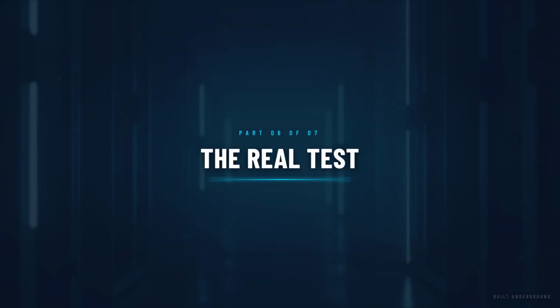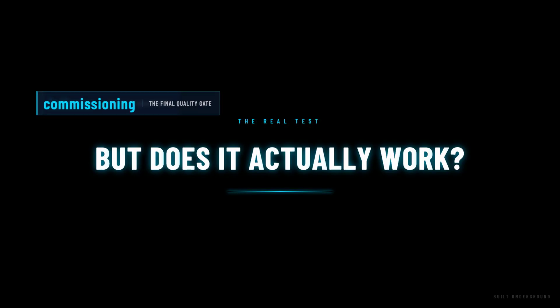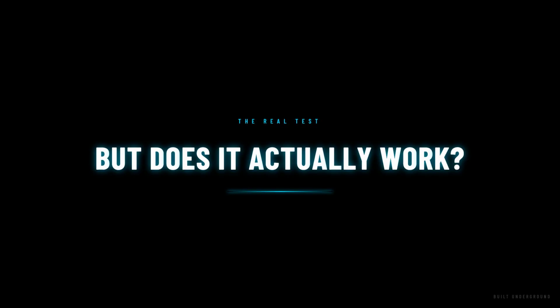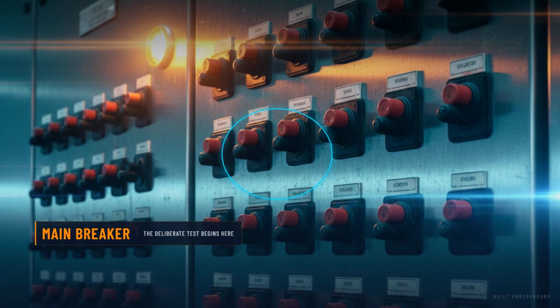The ultimate test of redundancy is not a component failure. It is a full facility failover test during commissioning. Engineers deliberately disconnect the main power supply and verify that the entire building transfers to backup power without dropping a single server. Then they deliberately fail the backup and verify that the secondary backup takes over.